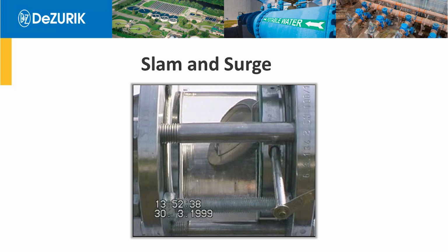And what you're going to view here in this video are a couple things. First of all, we're going to shut off the pump. You're going to hear the breaker trip. There's going to be a noise associated with that. And then we have that liquid that flows away from the pump station as a downsurge. One critical period later, that flow reverses and comes back to the check valve.